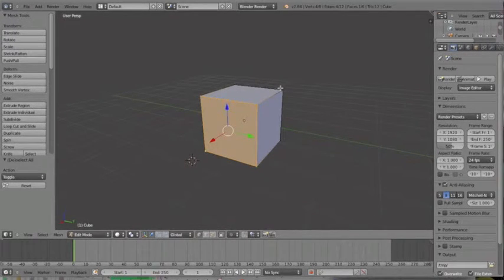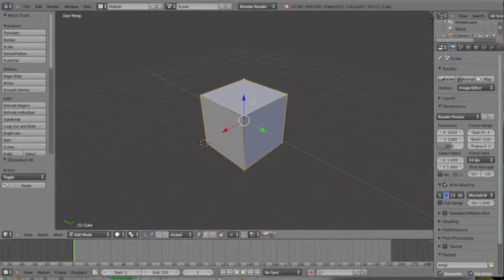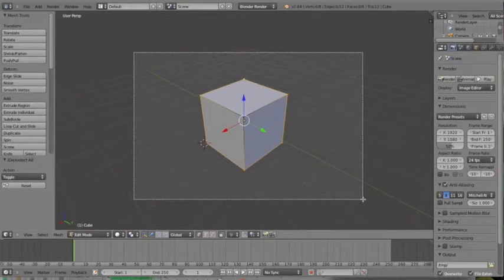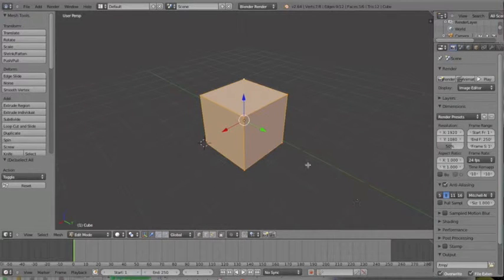These work just like normal objects, so if you want to select more than one, you just have to hold Shift and right-click on the point you want to select, and remember that you can deselect by shift-clicking again on an already highlighted point. Also, while in edit mode, you may need to use the box tool. This can be used by pressing Ctrl B for box. This will allow you to click and drag a box around a section of your mesh. The area inside the box will then become selected. Holding Shift when you click will deselect the objects inside the box.